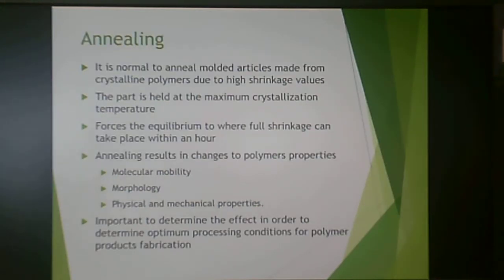So I mentioned that it can take up to 3 months for something that is semicrystalline to fully crystallize. But there's a way around that, and that is through a post-processing step known as annealing. It's totally normal to anneal molded articles to promote that maximum crystallization. You take the part and you hold it at the maximum crystallization temperature, and this forces an equilibrium where all of that crystallization can occur within about an hour.